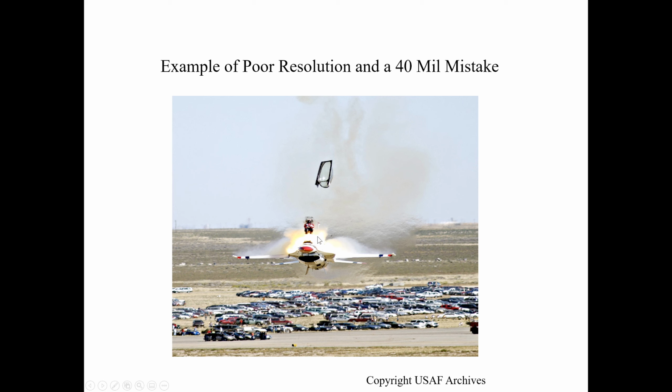This is an Air Force Thunderbird. Anyone who flies an airplane knows that on the altimeter you have to manually set the pressure altitude. Well, this pilot went to an air show before, set it for a certain altitude, went to a different elevation air show. He didn't change the altimeter setting, so all of his computers and all of his instruments were telling him he was flying 1,000 feet higher than he actually was. When he went to do this maneuver, he physically did not have enough altitude to complete it, so he had to eject. This is not a mechanical failure. This is pilot error.